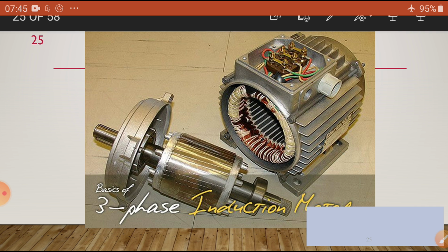At that condition, whatever power is taken from the supply is W0, that is the sum of the two wattmeters W1 and W2. In this case, we are going to use the 2 wattmeter method, and one voltmeter is connected across two lines and one ammeter is connected in series to one phase.